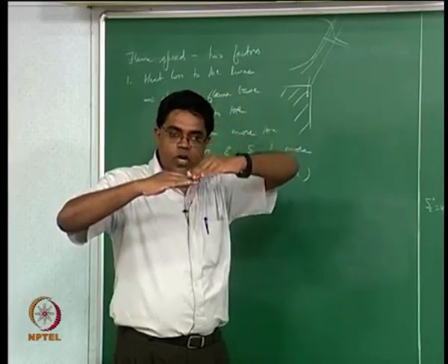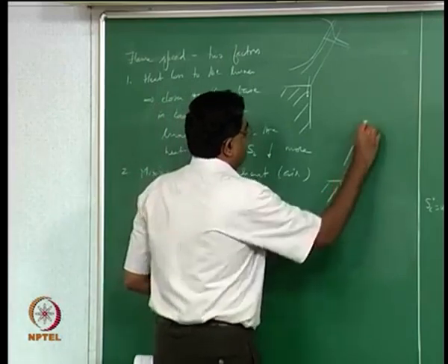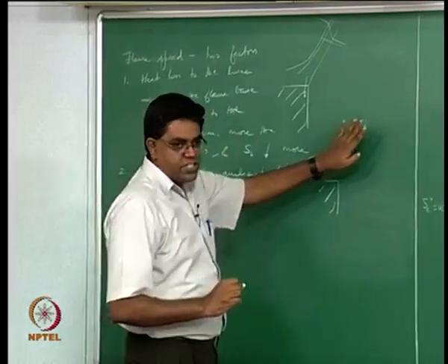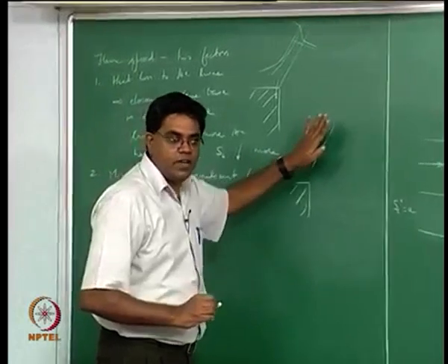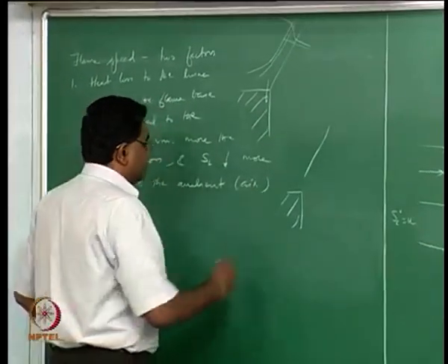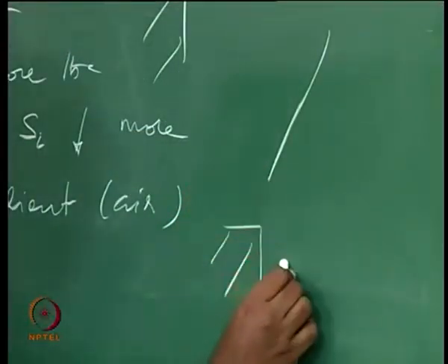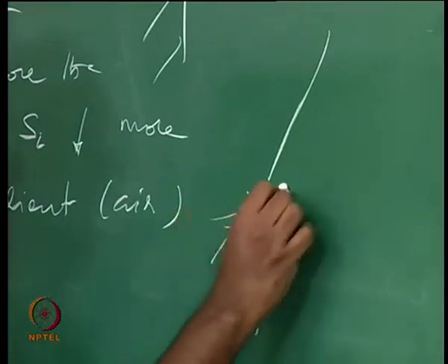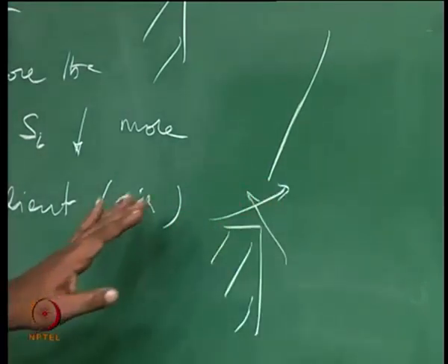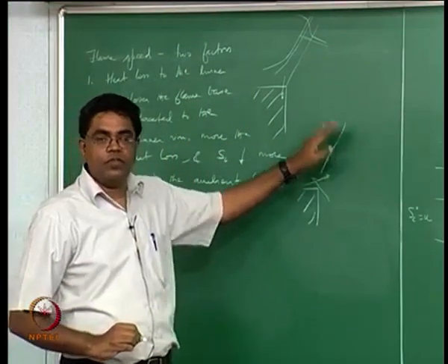Okay? So if you now have a flame that is progressively further out, and for this purpose it's sufficient for us to just draw a line to represent the flame. Let's not worry about its thickness, right? It is thicker and so on, that's fine, but what you're looking at is this distance. The more this distance, the greater is the mixing of the reactants with the ambient, right? What's the consequence of this for the flame speed?